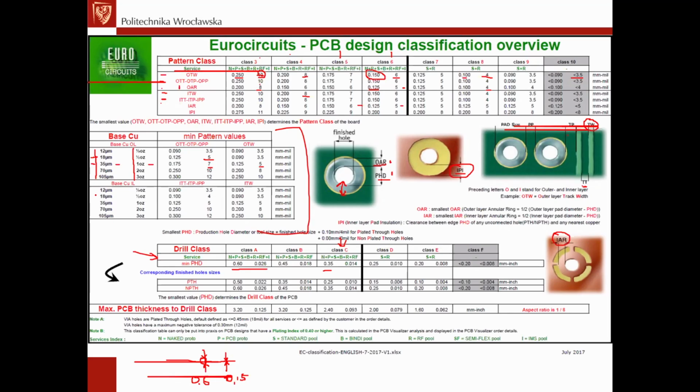For the inner layer, the technology is slightly milder. So even if for the outer layer you are forced to keep the distance between tracks, or between track and pads, at 7 mils with this 35 microns, at the inner layers you can be more fine, more accurate, with 5 mils or 0.125 millimeters.